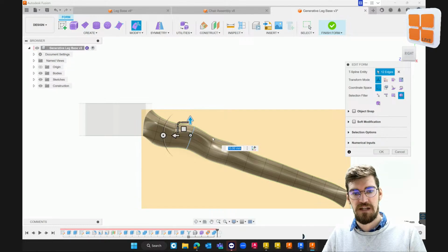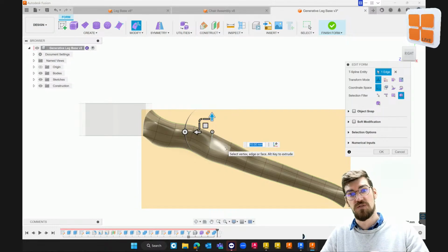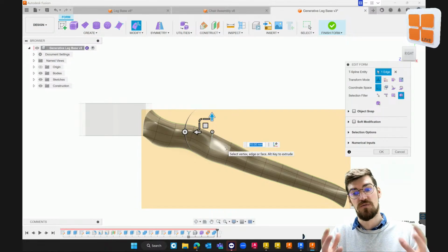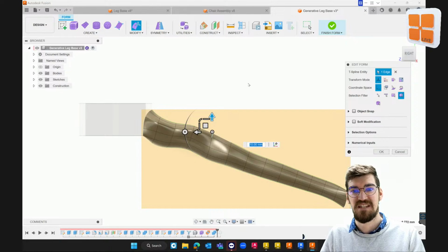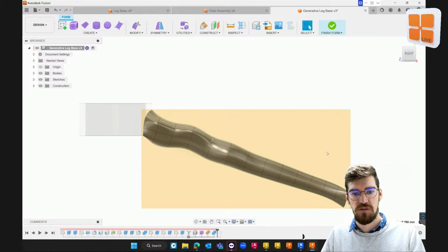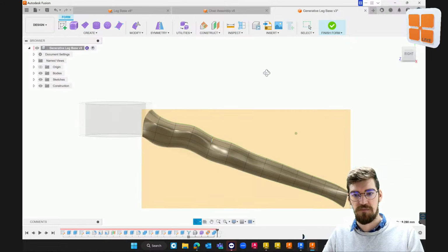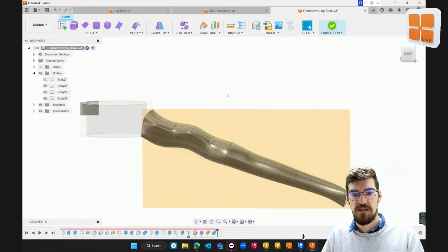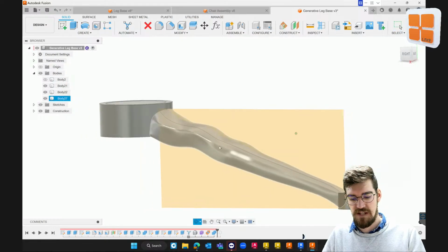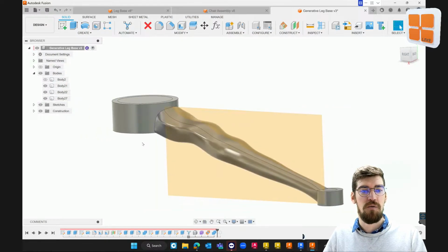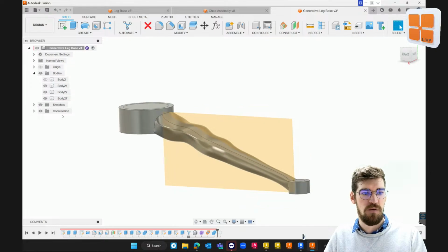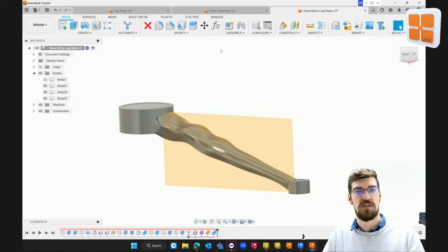as I say, we can make any adjustments we want to the positioning of individual surfaces, edges, or nodes within the T-Spline model itself. I'm going to cancel out of here because I don't actually want to make those changes to the particular component. But once I'm happy with this, I've saved those changes anyway, it doesn't matter. Once I've made the changes that I want to, particularly to this one, I could then go in and force a circular pattern once more around here.